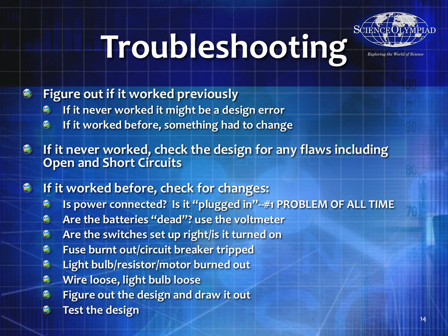So these are all the types of things that, if you're given a hands-on experiment, check your voltages to make sure it really is turned on. Make sure that it really does have voltage. Make sure the switches really are set up right. Look and see if there's a fuse burned out or a circuit breaker tripped. Look to see if the light bulb, the resistor, or the motor is burnt out. A very common thing, let's face it. If you are in your house and your light bulb is working and all of a sudden it stops working and you flip the switch back and forth, that's what you check on.